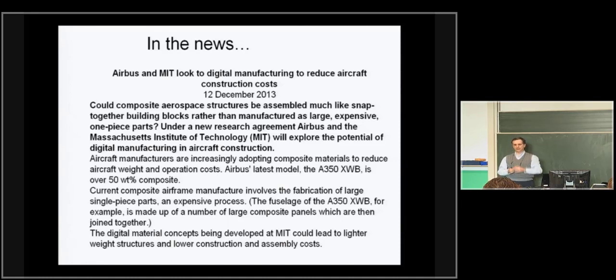Any other? We need to apply safety factors for composites with regulations. Okay, and that's actually indirect, but it's reasonable. The safety factors, or at least the requirements, are more stringent with composites, impact damage and so on. And that typically adds weight. And every time you add weight, usually you add, not proportionately, but you add some cost because you have more material you are putting in and more time you spend to put that material down. Other reasons? I want at least one more.